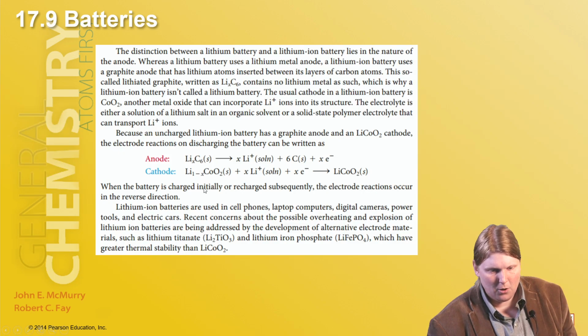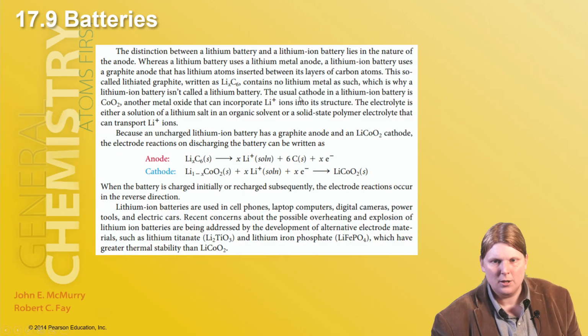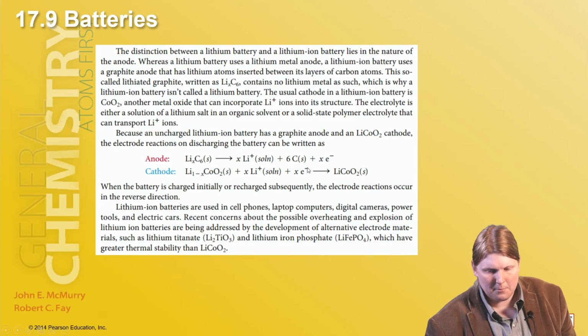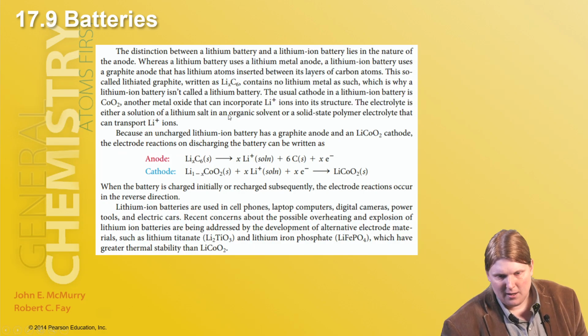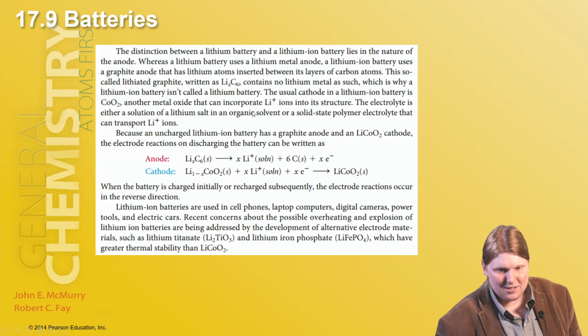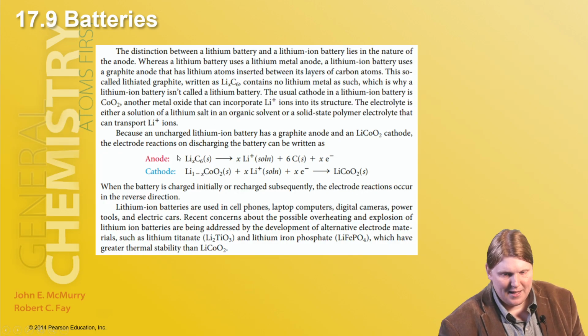All lithium batteries have a kind of puncture risk associated with them, and they should be handled with care, especially when they're damaged. They tend to swell up with gas as organic solvents change state and polymers break down, and other reactions happen inside the cell. It's typically how you know that that's the kind of cell these are. When they die, they tend to undergo swelling, heating or explosion.